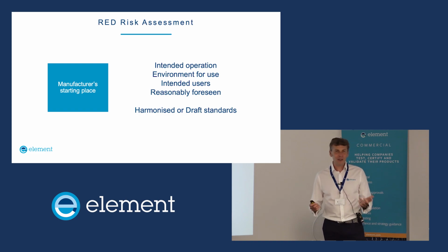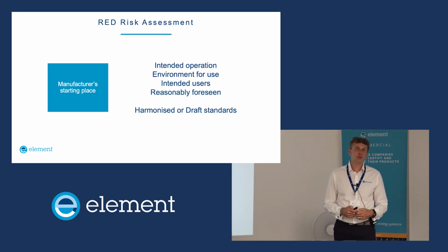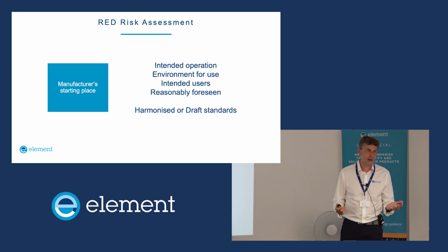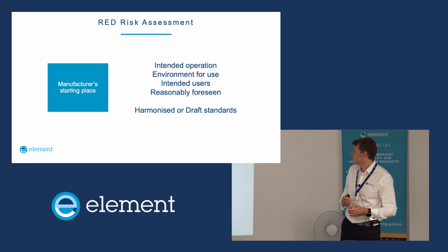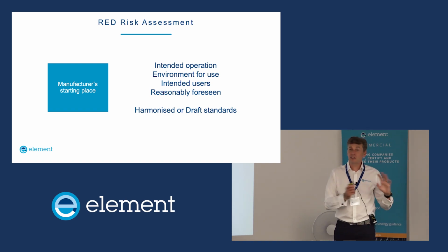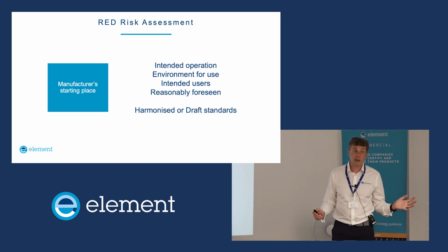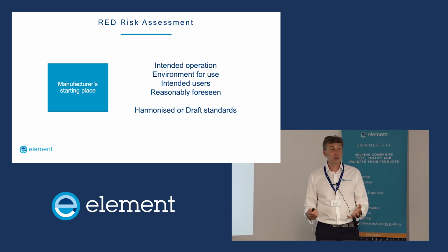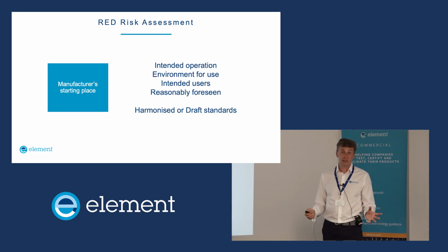That's not real. Everybody plugs their phone into their car all the time, and so not doing vehicle transients on something that's USB powered that somebody might take in the car is just crazy. If you've got harmonized standards, it gives you presumption of conformity, as I explained this morning. If the standards are not harmonized, you don't have presumption of conformity, so you put in your risk assessment why you chose that standard. And it might be a really simple reason.